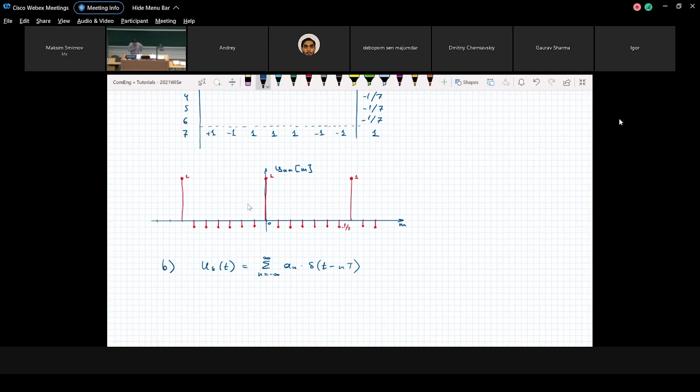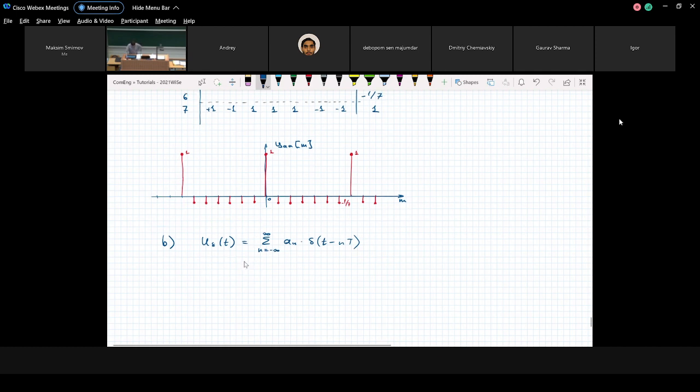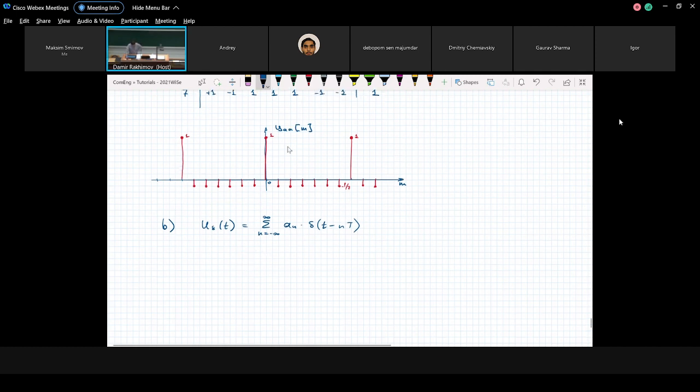And in order to get this autocorrelation function, we just use the discrete time autocorrelation function, and we normalize by the spacing between delta pulses. So we just keep the same shape of our autocorrelation function. We replace each pulse by a delta pulse and normalize by the spacing between delta pulses.